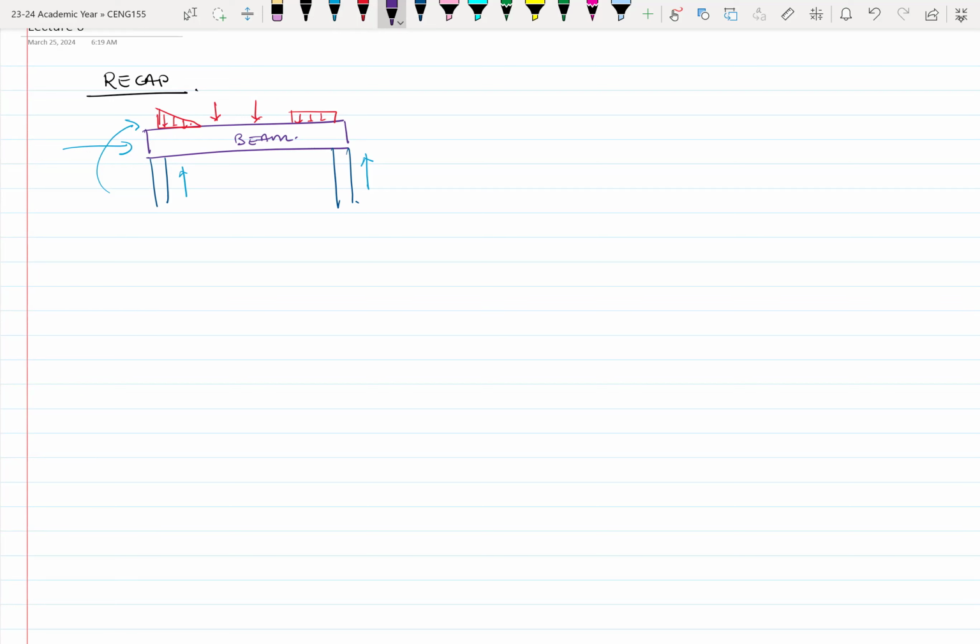And these forces, we have three of these. We have the axial, which is the horizontal. We have the shear, which is vertical, and then we have the bending moment. All right. So these internal forces or internal behavior is usually in equilibrium, and there's a reason the material remains stable, or it is as we see it, right? So that if it is a bar of wood, let's say a long piece of wood, it remains that way because the fibers within the wood are in a state of equilibrium. Okay.